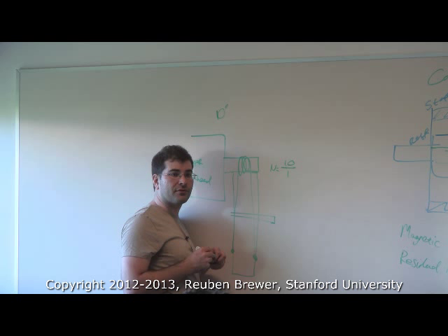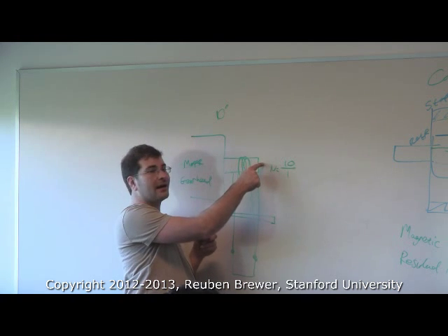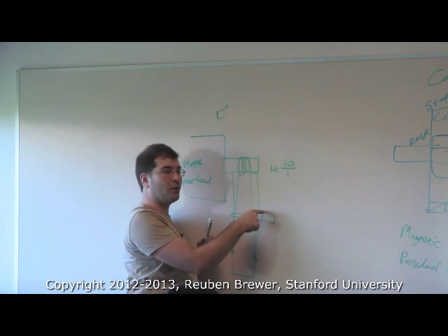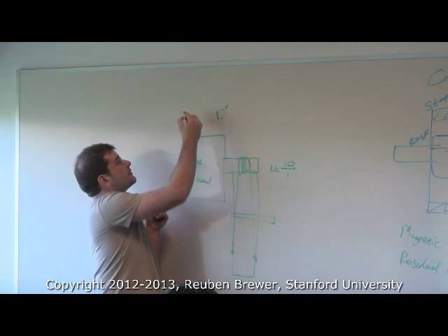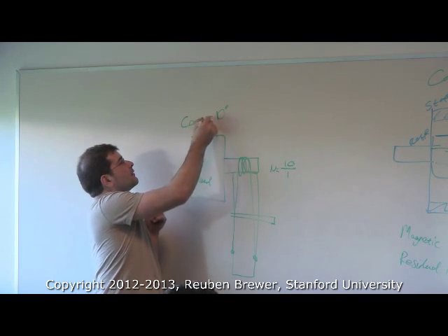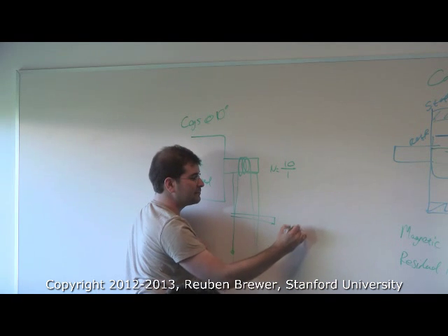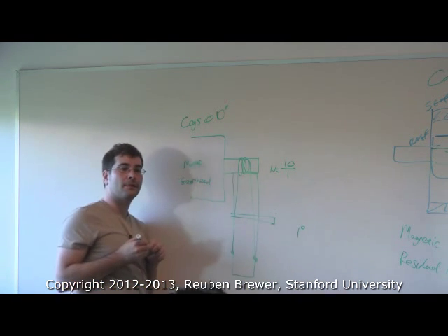I heard conflicting reports. So you have a 10 to 1, so this has to spin 10 times, the motor shaft spins 10 times to get one turn here. Okay, and I have little cogs. Yeah, 1 degree. So now I experience the cogging at 1 degree.